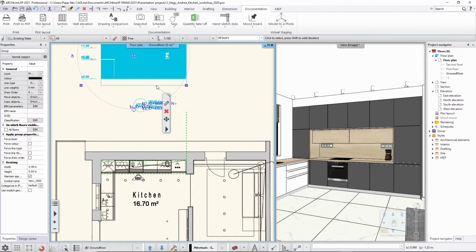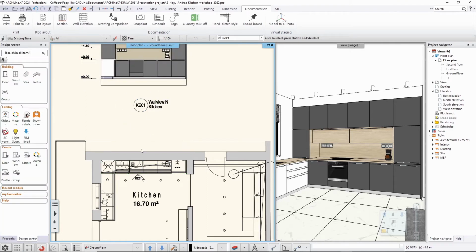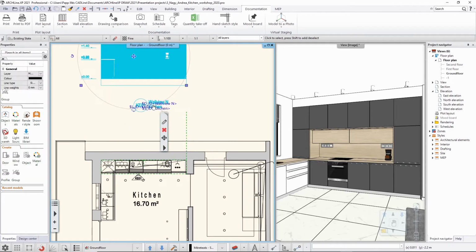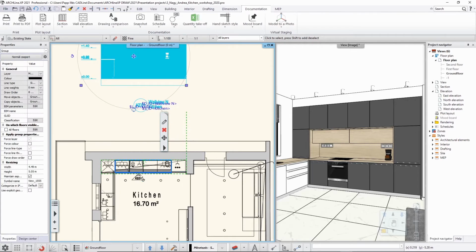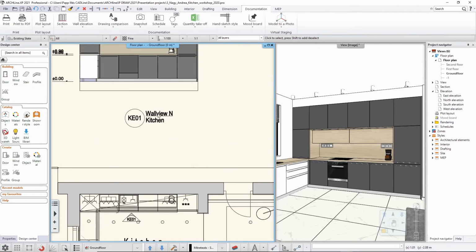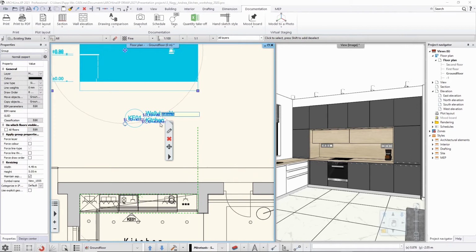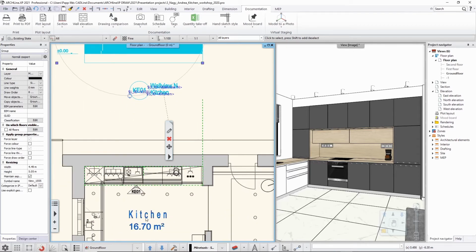It is easy to tell when you select an already placed wall elevation view. This tiny dashed line with the rectangle here represents the direction, the depth, and the interconnection with the placed drawing content on the drawing. So this is how they are interconnected. The software understands that they are there, and should I remove this one, the 2D symbol will go automatically wherever I placed it. Also, I can change the wall view name and the room name, for example. Now the room name is a good thing, as it is automatically inherited from the room's name, so you didn't have to do anything with that.